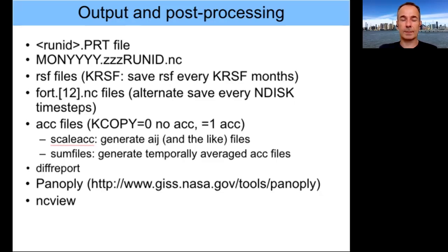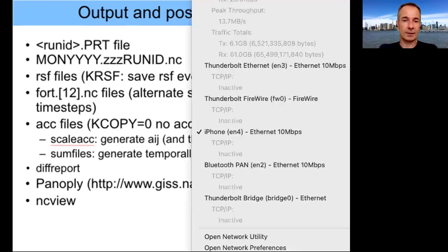And we have two files so that we get protected from the case that the model crashes during writing of those Fort files, and then this becomes corrupt. So if something like this happens, let's say fort.2 became corrupt, then the model cannot start from that, it will keep crashing. You delete fort.2, copy fort.1 into fort.2, so you have two files which are exactly identical with a different file name. The model checks, sees the same date, picks one at random, and continues from there. You just need to make sure that you are deleting the corrupt file and not the proper file.